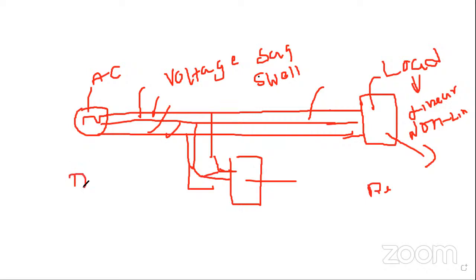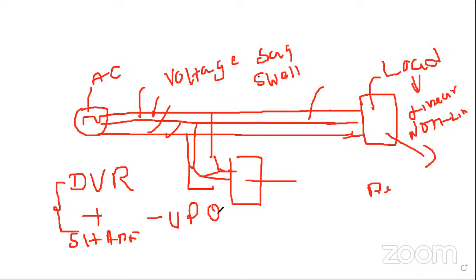In the series connection, we can call it a DVR, Dynamic Voltage Restorer. So a combination of DVR and a shunt active filter, or StatCom, DStatCom, distribution side StatCom. The combination of both these we can call UPQC, Unified Power Quality Conditioner, or Unified Power Flow Controller also. So these are the things we will work on.